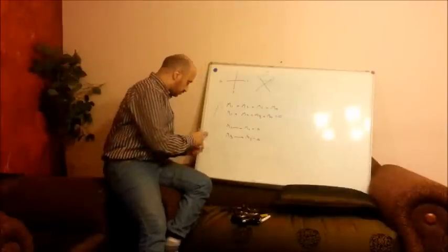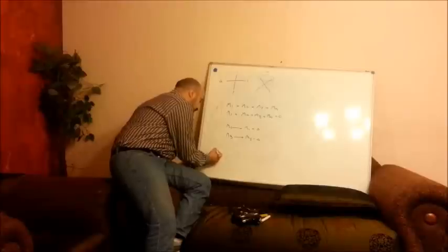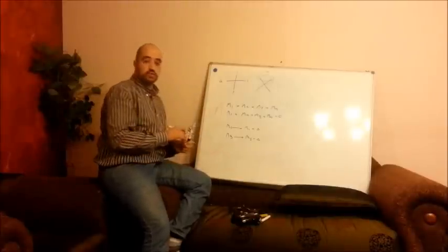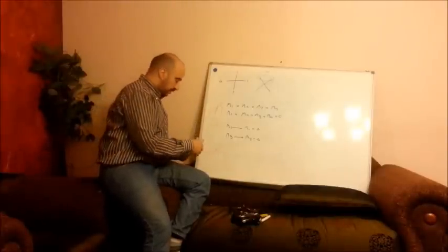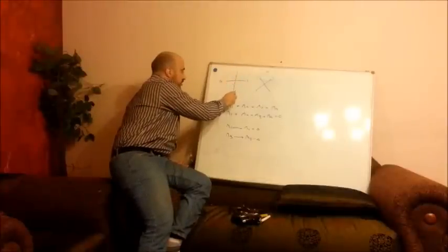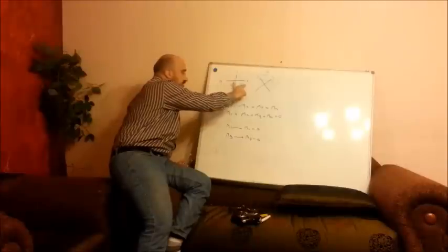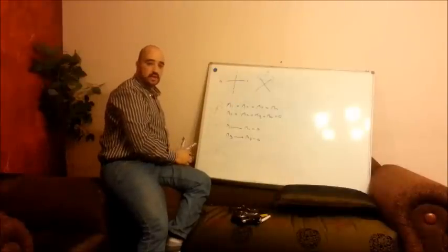So the third rule here: if we want to rotate the quad, we change the RPM of two motors by increasing one axis and decreasing the other axis of motors.